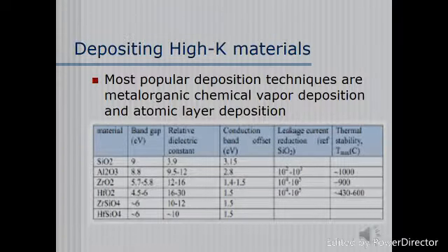By using dielectrics with high constants, usually greater than 10, we can keep the thickness to normal conditions while increasing the capacitance. The most popular high Kappa dielectrics are the ionic transition metal oxides. Transition metal oxides are usually used on crystallized silicon, then thermally grown. To create dielectrics with the wanted electrical properties, the dielectric has to have great interfacial and bulk properties with uniformity.